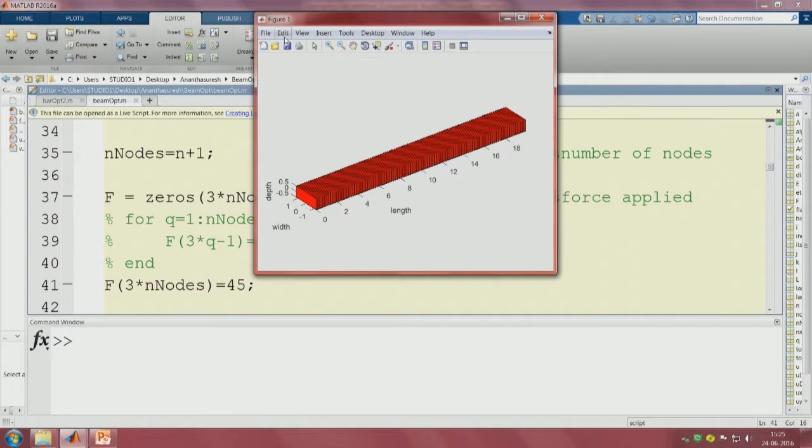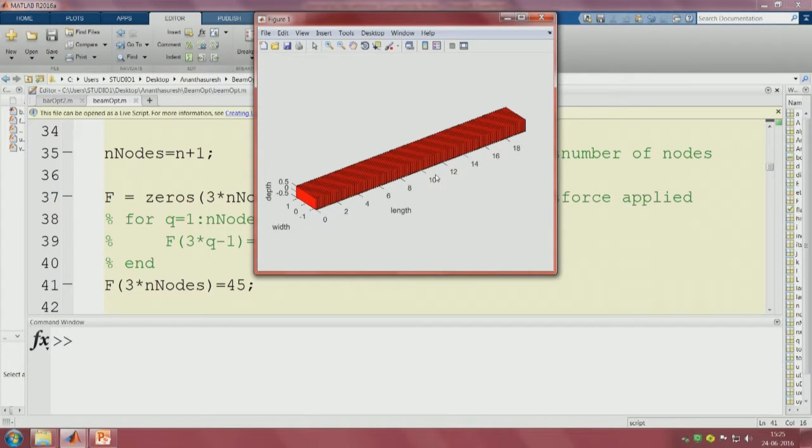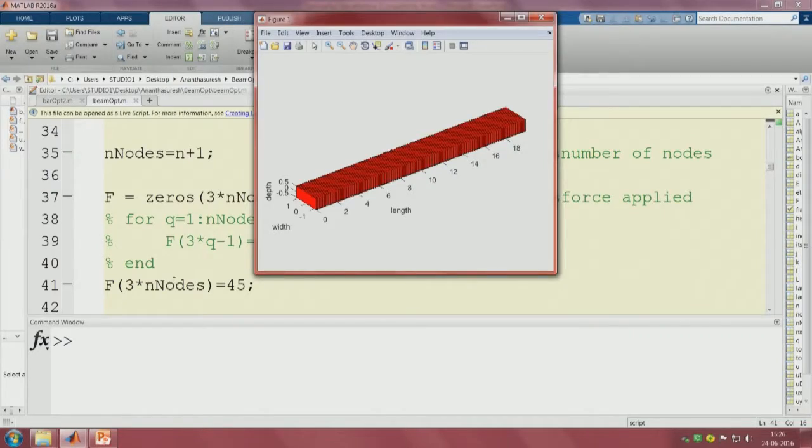So, we have constant moment. When there is constant moment, we got constant area of cross section, that makes sense. If you go back and look at the analytical thing, constant moment, only moment we applied for a cantilever at the end, then the bending moment is the same throughout the beam, and hence optimality criteria method would tell you that area of cross section, because we assumed second moment of area equal to area of cross section some alpha d square by 12, that is just an alpha, beta equal to 1, then what we get is uniform cross section, that is what it is, it converges very quickly.